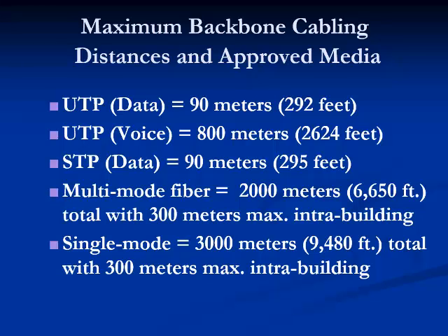Maximum backbone cabling distances and approved media include, for UTP data, 90 meters or 295 feet. For UTP voice applications, it's 800 meters or 2,624 feet. Screened twisted pair is also 90 meters. Multi-mode fiber is 2,000 meters. Single-mode fiber is 3,000 meters.